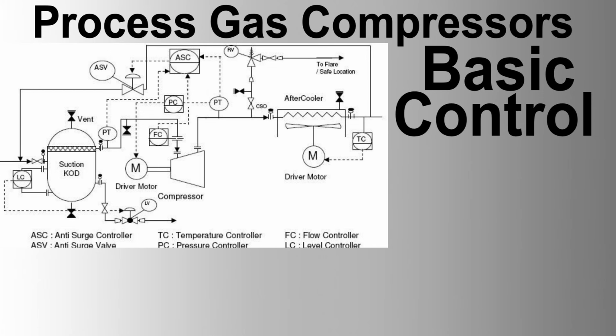B. Signals from the DCS. Speed feedback, actual speed of the compressor. Current feedback, real-time motor current. Voltage feedback, real-time motor voltage. Vibration data, real-time vibration data from the compressor. Temperature data, real-time motor and compressor temperatures. Fault alarms, real-time fault and alarm status.